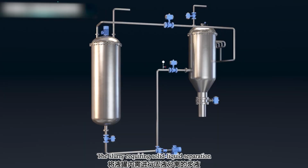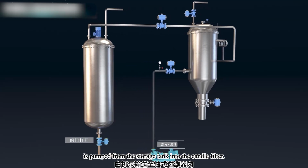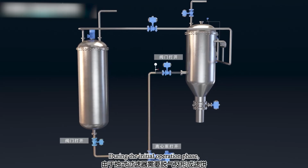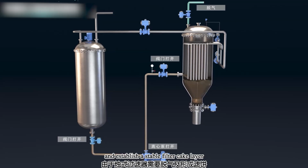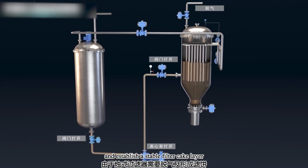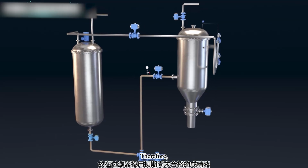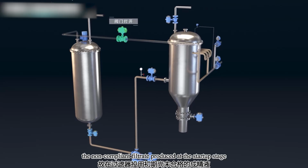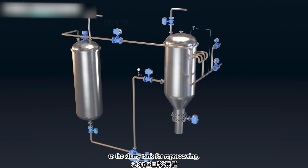The slurry requiring solid-liquid separation is pumped from the storage tank into the candle filter. During the initial operation phase, the filter must undergo a degassing process and establish a stable filter cake layer to achieve the desired filtration precision. Therefore, the non-compliant filtrate produced at the startup stage must be recirculated back to the slurry tank for reprocessing.